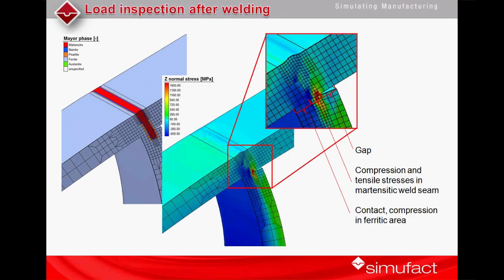If you zoom in on the weld zone, you can see the narrow area where the material was molten and it's actually joined. Then if you look at the upper right-hand picture, you can see that on the right-hand side, that area, the metal did not melt, so it was not joined. So if you load it up, it just comes free, you open up a gap.